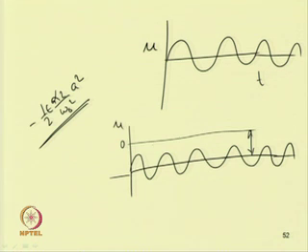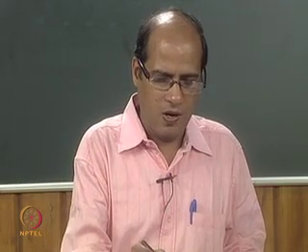So, the oscillatory motion no longer oscillates about the line u equal to 0, but it will oscillate about this point, that is minus half epsilon alpha 2 by omega 0 square a square. So, in this case also one can study the subharmonic and superharmonic resonance condition. So, instead of taking the forcing term of the order of epsilon square, one can take it of the order of the linear term, that is by writing the equation in this